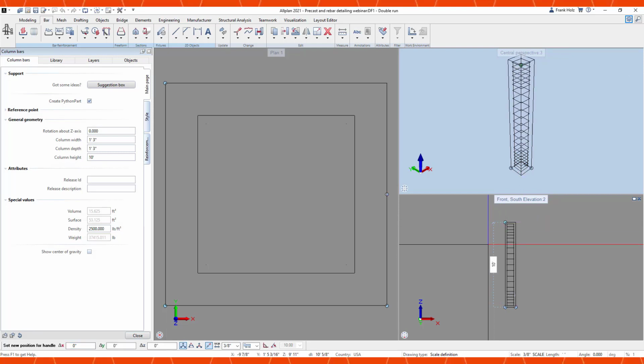this Python part, drag and drop it, just like we did with the skewed end culvert, turn off the geometry so we get all that special geometry that's already been modeled for us, or maybe we modeled ourselves. And this will just add that reinforcement for us. And you can see that it's maintaining those stirrup areas at the end, the stirrup area at the middle, that I can easily drag and set into place.